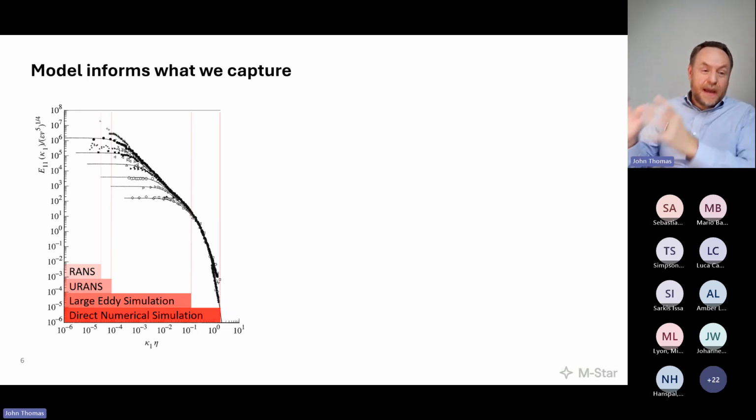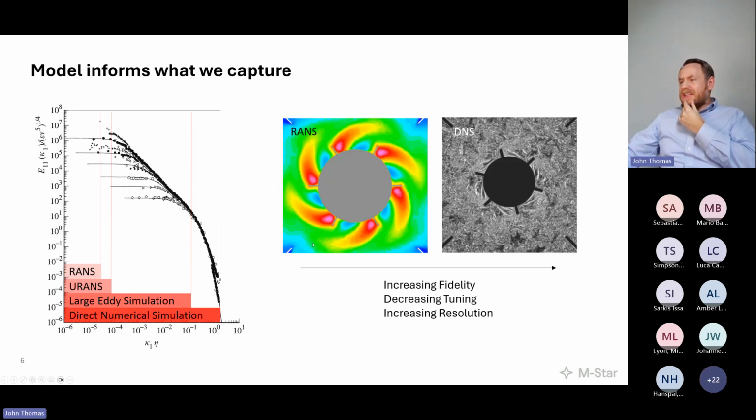And I'm going to be more aggressive about that point momentarily when I talk about some recent advances in the literature where there's almost not a point. I'll speak to that again with some papers that just came out last week. So foundationally, we're not talking about just a watercolor picture of flow at some snapshot in time with some everything-but-nothing turbulence model. We're going to be resolving everything, and we're going to leave nothing behind, as it were, as we go to DNS, and maybe leave some things behind as we go to LES. I'm not trying to throw a bunch of shade on RANS. I'm saying, what's the point when we can do this these days? And I'll speak to that more forcefully with some compelling validation from the literature.